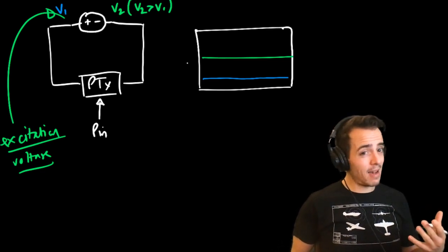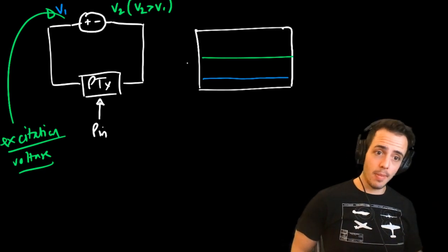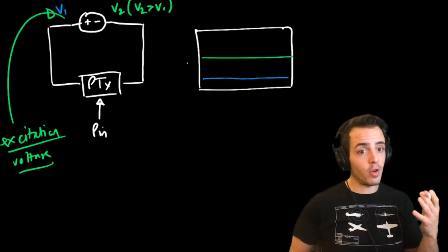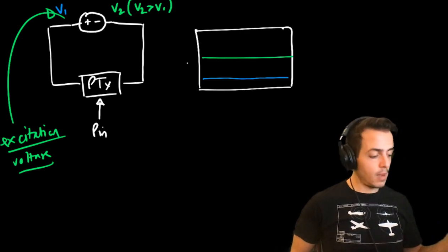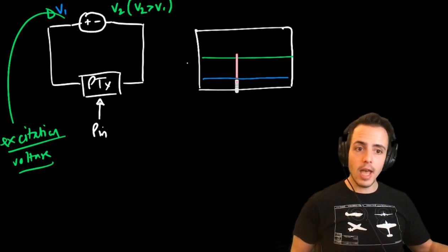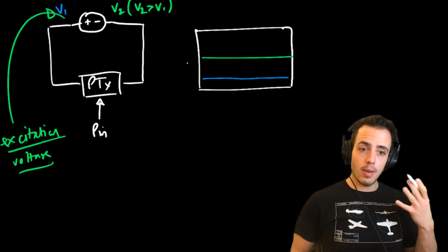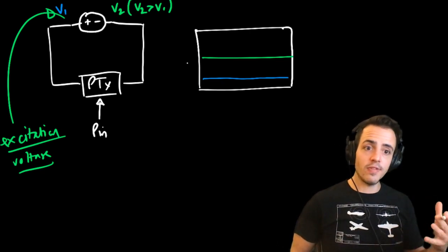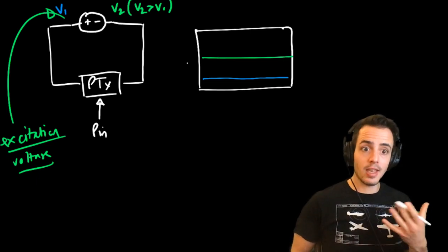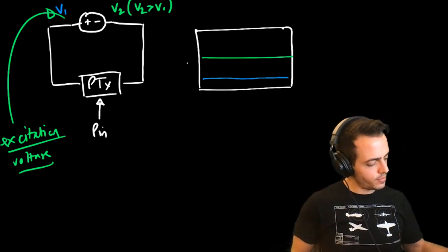Now that's not often going to happen because we'll be doing it in a different setup. We might have supply voltage fluctuations, or we might want to change our supply voltage to get a different scale out of our transducer. So what we more often need to do is take our output and divide it by the input voltage to get the gain across the transducer.